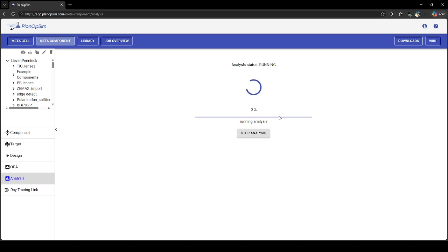So to do this, we run our metasurface designs using various approximations. The approximations we use here, in combination with the powerful servers on our side, allow us to simulate record-breaking sizes up to around 1 billion scatterers within single metasurfaces. This is 1 billion individual microstructures over a total area. If we use a unit cell size of 500 nanometer, that would be around a 15 millimeter metasurface component.